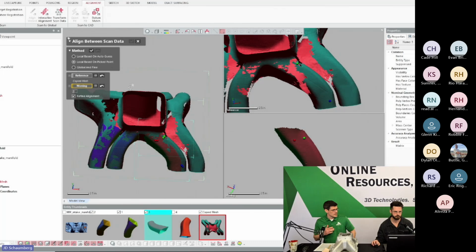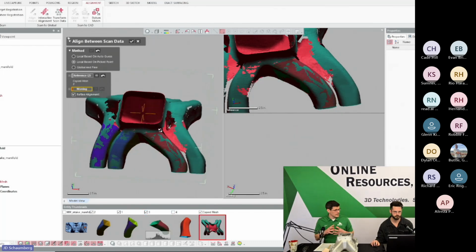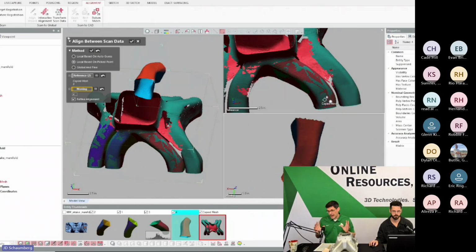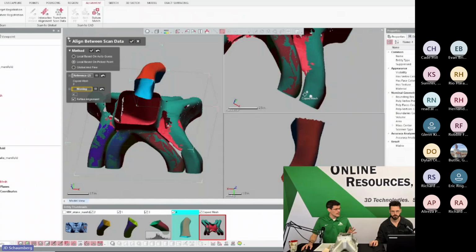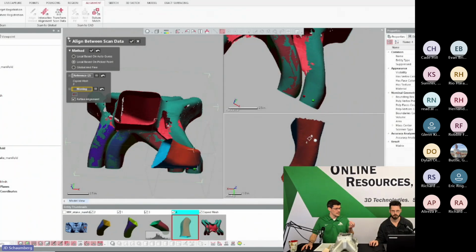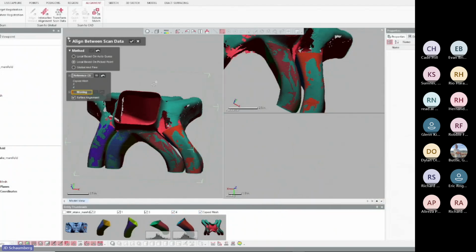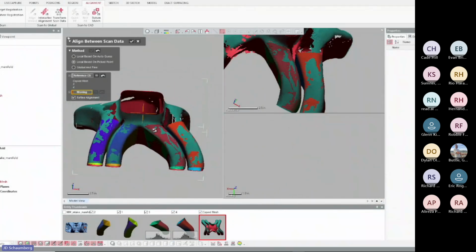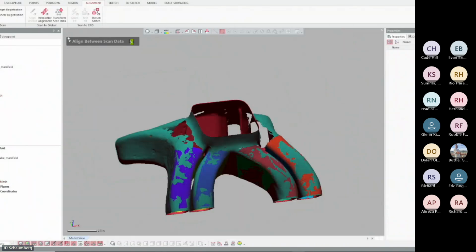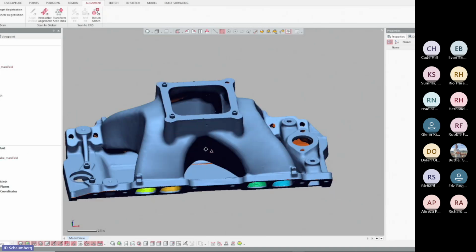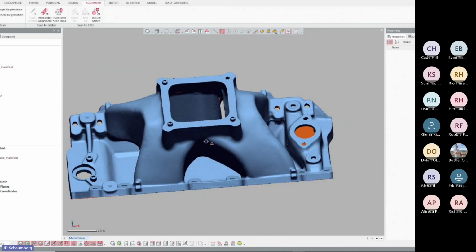And this is one of the tools that Cunningham Pattern really speaks to, as the alignment capabilities of data and the powerhouse of Design X, and taking whatever data you need and aligning it different ways to get a single STL. Right. This could be a few scans of the same part. This could be the example that we're doing here. You can do any sorts of alignments between many different meshes. So there, now I have the silicone plugs aligned and registered correctly relative to the internal surfaces of the ports, and as a result, also registered correctly with the external surfaces of the manifold as well.